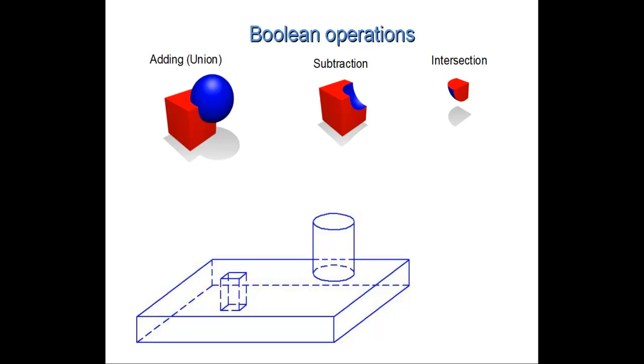The object consists of a thick base with outgrowth and a hole. We subdivide the object into three primitives, say two parallelepipeds and one cylinder, A, B, C. Note, the decomposition can be done in another way too. Then we model all the primitives either by kinematics operations or by using the primitive library, and finally, applying the Boolean union and subtraction, we can obtain the desirable model E. In the K3 system, all the features described above are executed by a set of appropriate functions.